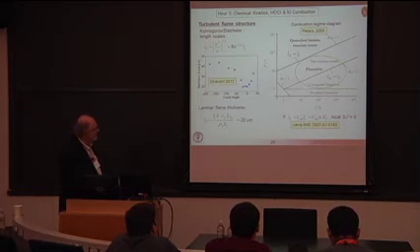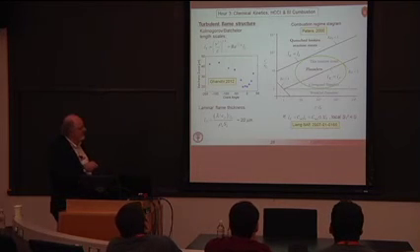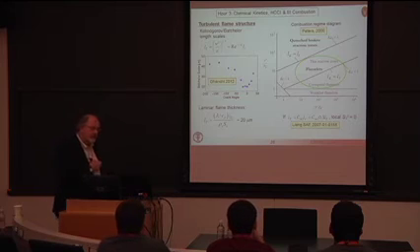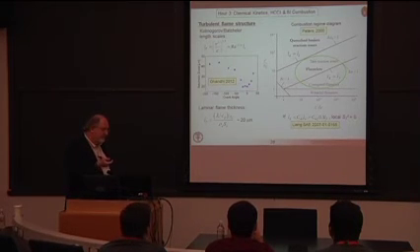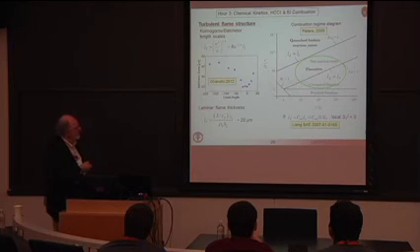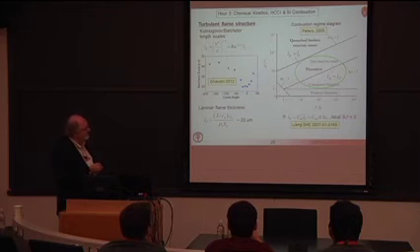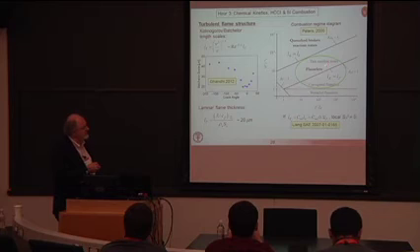And typical engines operate in a range here that are characterized by flamelets. So basically you have laminar flames that are propagating into this mixture, but they are all contorted and have very high surface areas. So the surface area that corresponds to the fuel air to products conversion process is much increased by the fact that these flames are corrugated and these thin reaction zones combine to form a turbulent flame.